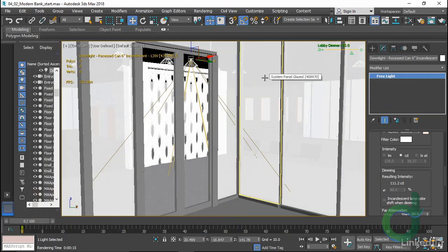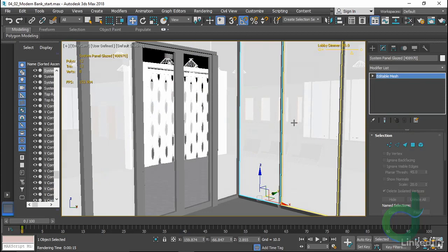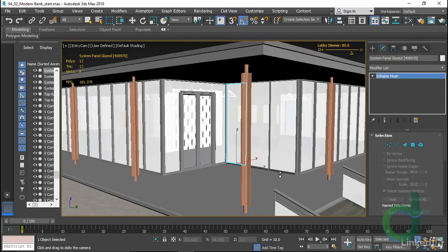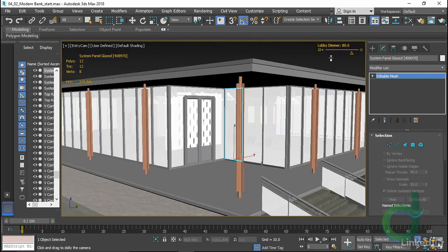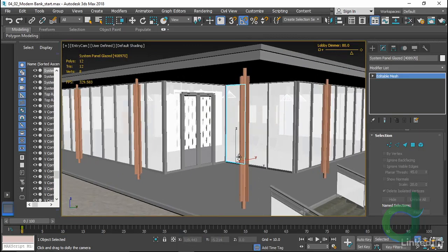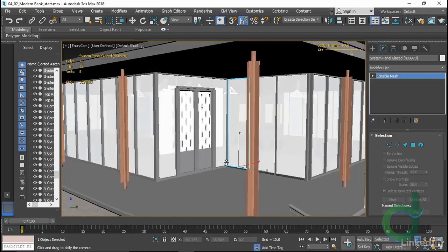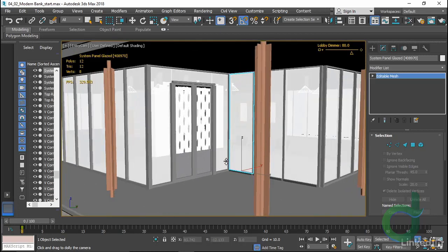And again, here's the cool part. I'm in my camera view, and I can have anything else selected. I'll dolly the camera around, and that manipulator is persistent on the screen. So without having to go and select the objects, or maybe they're hidden or I can't see them or whatever it is, I've got control over the lighting bank in that scene, and we can animate one manipulator to turn on those lights in an animation.